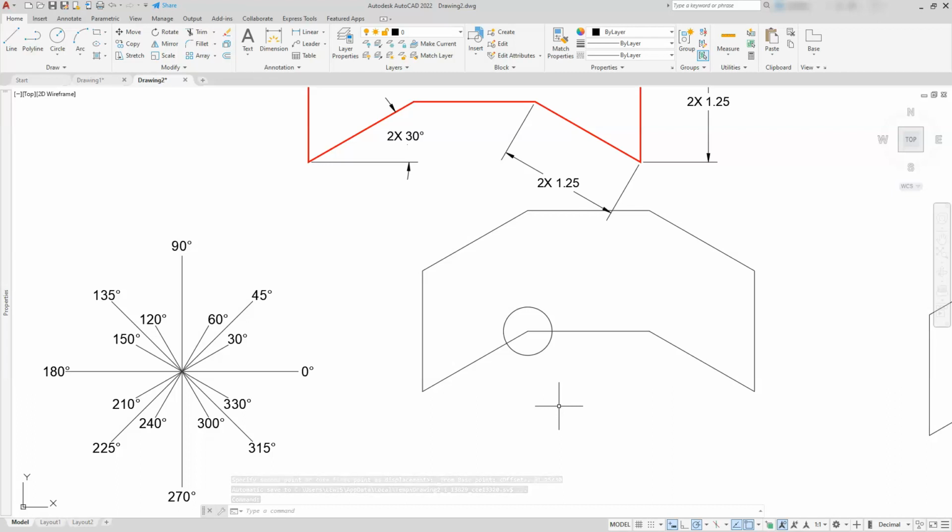So if I did not physically have that endpoint sitting here, yes, I know where I want it to go from this endpoint, and I want it to be located there at that angle. I can type in all the syntax and get it. When you're using these modify commands, one of the other things you're going to see is that you do have the option of pre-selecting things. Once we go over the move command and copy command in another video, I will definitely show you more about that. But just keep in mind that anytime you're using any of these modifying commands, I can pre-select what I want to do. So I can select this object here, and then go to move, and it's going to skip that step of selecting my objects.